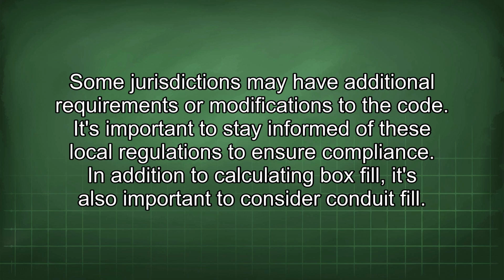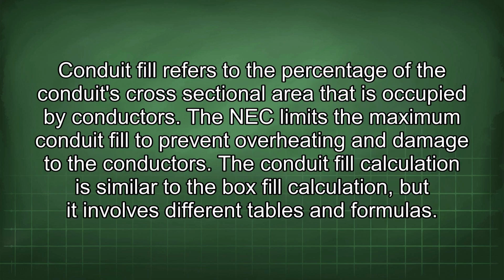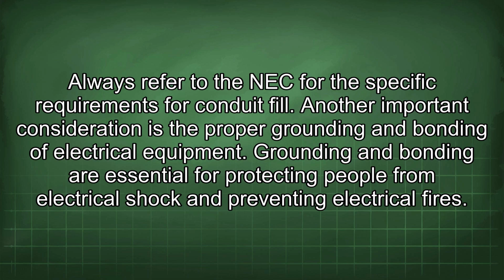In addition to calculating box fill, it's also important to consider conduit fill. Conduit fill refers to the percentage of the conduit's cross-sectional area that is occupied by conductors. The NEC limits the maximum conduit fill to prevent overheating and damage to the conductors. The conduit fill calculation is similar to the box fill calculation, but it involves different tables and formulas. Always refer to the NEC for the specific requirements for conduit fill.